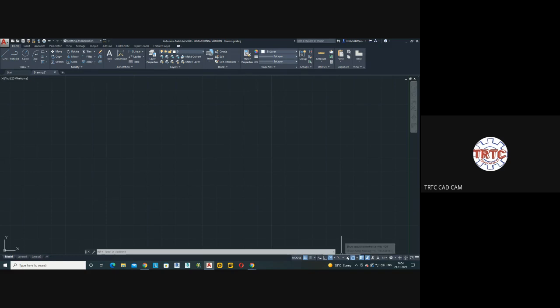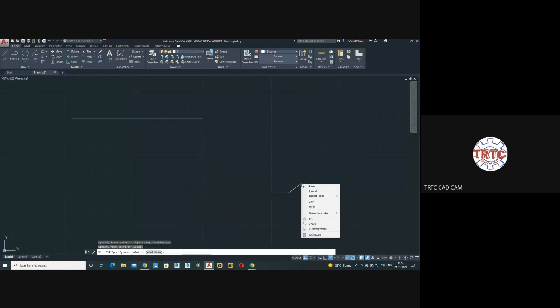This is your object snapping. What does object snapping mean? If I draw a line like this, you can see one green color line will tell me whether I'm going exactly in a straight line or not. If I turn this on and just touch this point and move down, you see one green color line is being made. It is tracking that I'm moving straight from the point, starting from here to here.